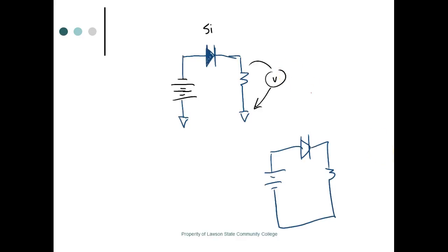The problem we have is the 7/10 of a volt, number one, only comes into play when it's forward biased. It doesn't come into play when it's reverse biased. Normal tendency, people look at silicon and they say 7/10 of a volt. And another thing they don't do in this class is look to see if the dang thing's forward biased or reverse biased.